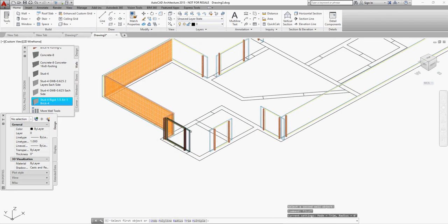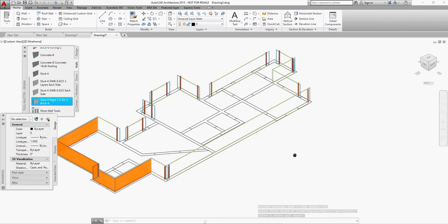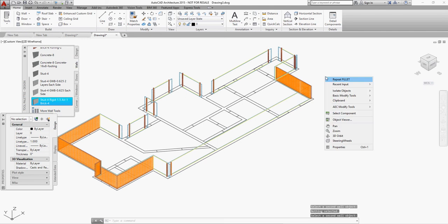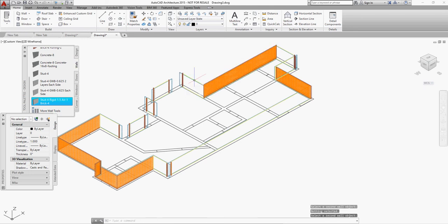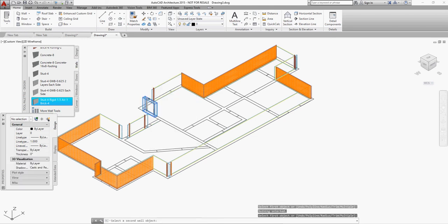This one looks like it also added baseline. So I almost need to set all the walls and say I want them to be left. So what I can do is I can come over here and I can say, okay, I just want to select the walls. And I want to make sure that all the walls, the baseline is set to left. Then I can do it all in one shot. Okay, and then just that one there.